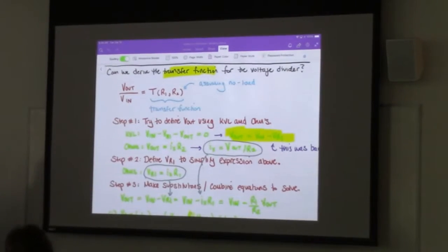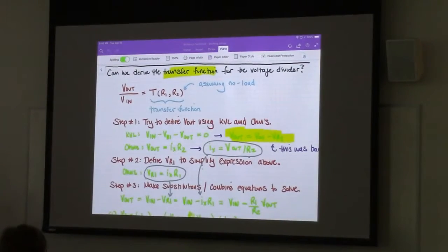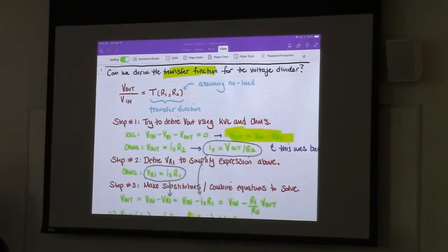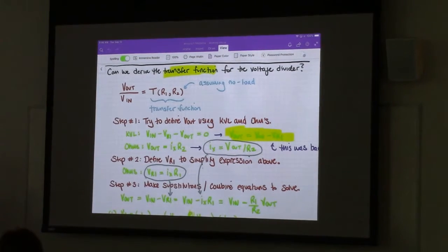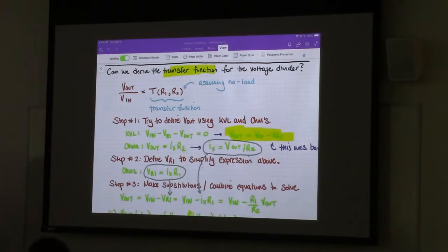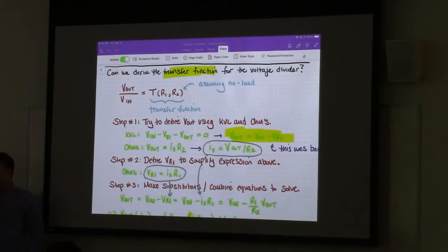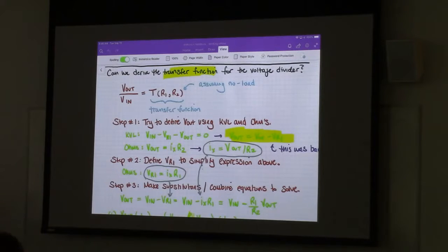transfer function is. Yes? Is the voltage divider strictly limited to splitting into only two parts, or can it be multiple? Well, you can build something like a voltage divider that splits into multiple parts. The thing about that is that only one of the values will be referenced to ground. So some of the other values will be differential voltages, right? Because only the last resistor before ground will be referenced to ground. Generally, the definition we're going to use is two. If it were more, I don't know if I would use the term voltage divider, at least the textbook wouldn't use it that way.